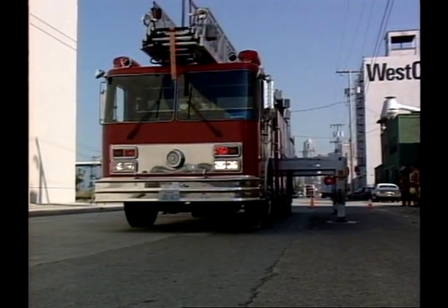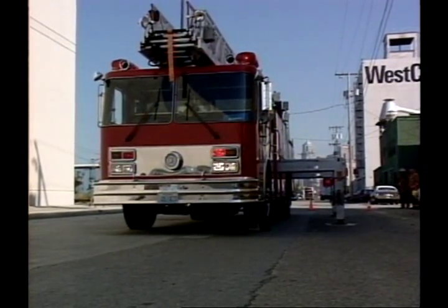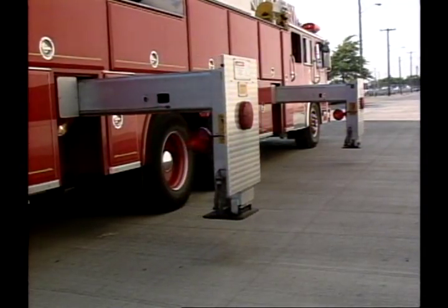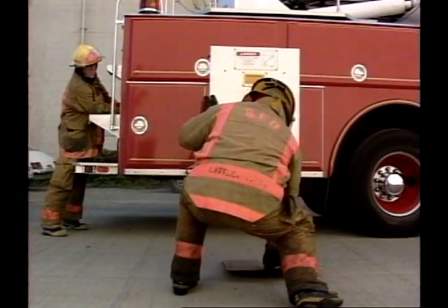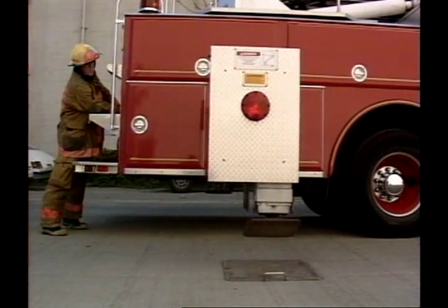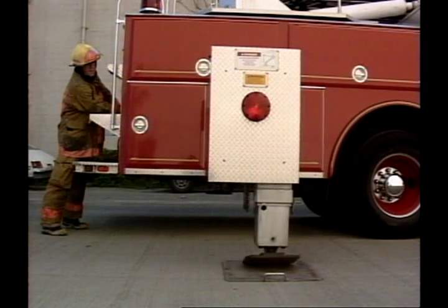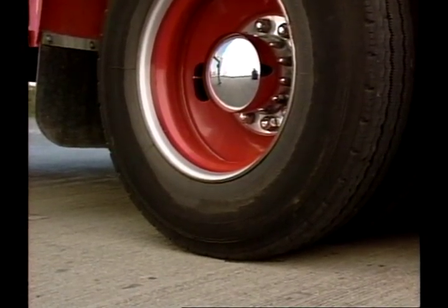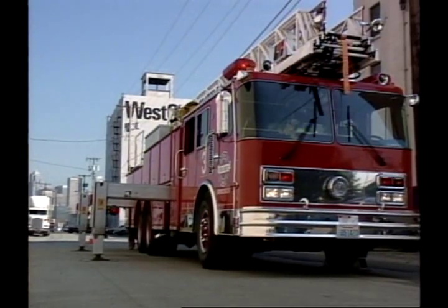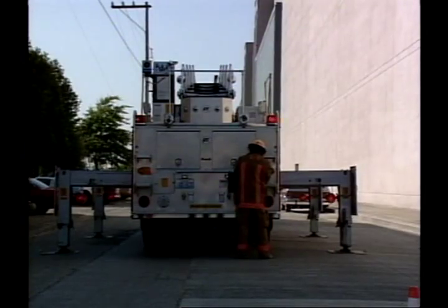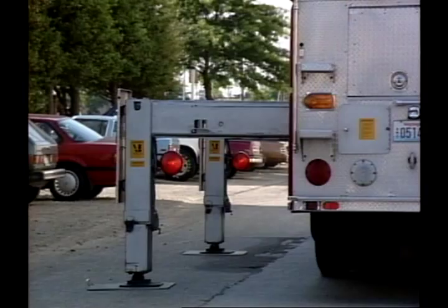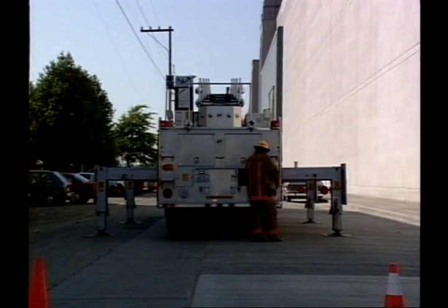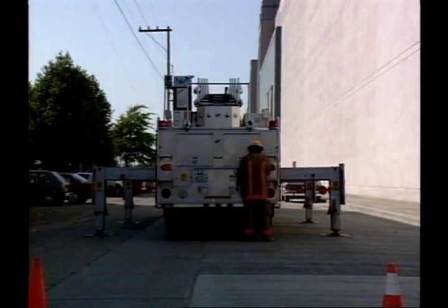On level ground, you may lower either side first. Lower both stabilizers on one side of the vehicle before you lower the other side. Lower the stabilizers until the pressure lifts the truck up slightly on that side. One way to observe this is to check the tires. When the tires no longer bulge at the bottom, the truck is slightly lifted. When all the stabilizers are on the ground, alternate between the sides to raise the vehicle to the working position. Once again, this will vary by manufacturer.